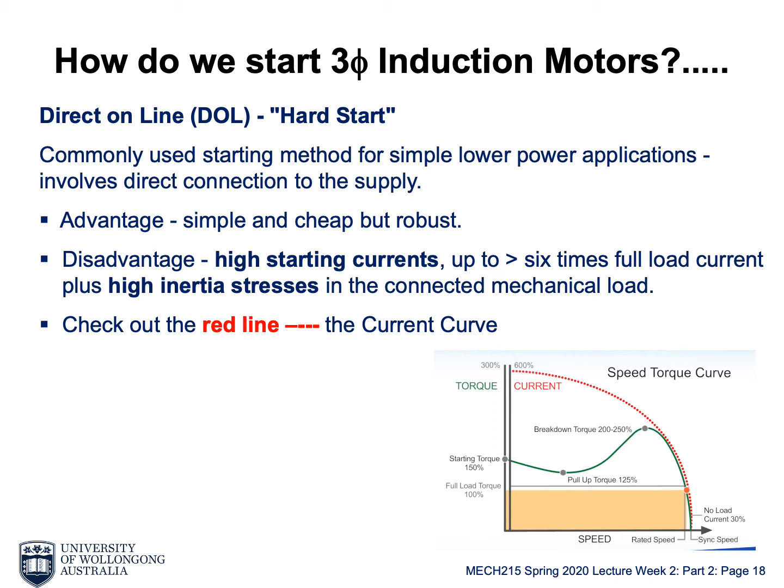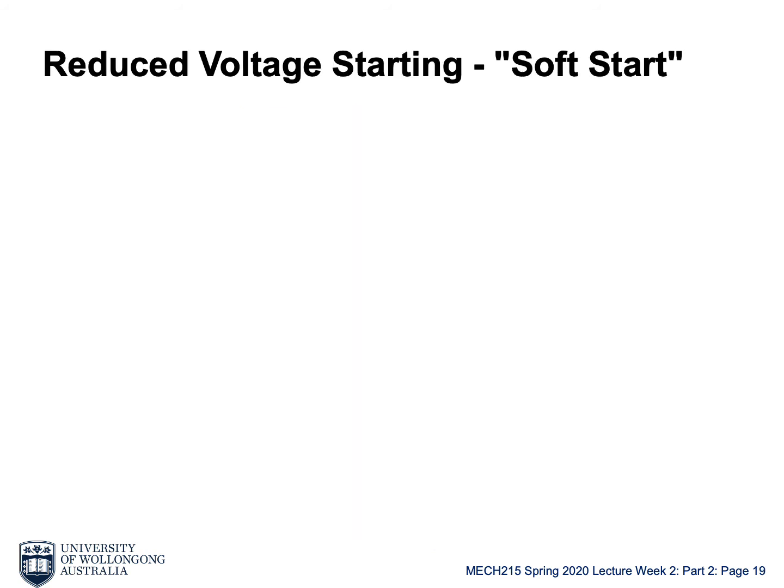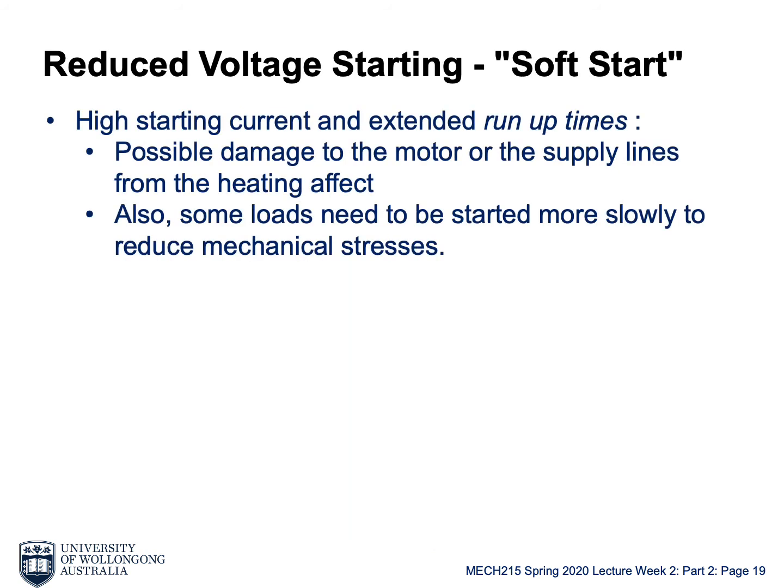So that's the simplest way to start. Basically, we don't do anything. We just connect the motor directly to the power and turn it on. But there must be a better way, particularly when you have a heavy payload and your motor will take a long time to start. With this direct hard start, there might be some problems for the system. If we just connect the motor directly to the supply voltage, at the beginning there will be high voltage and also high current, which potentially causes that hard start problem.